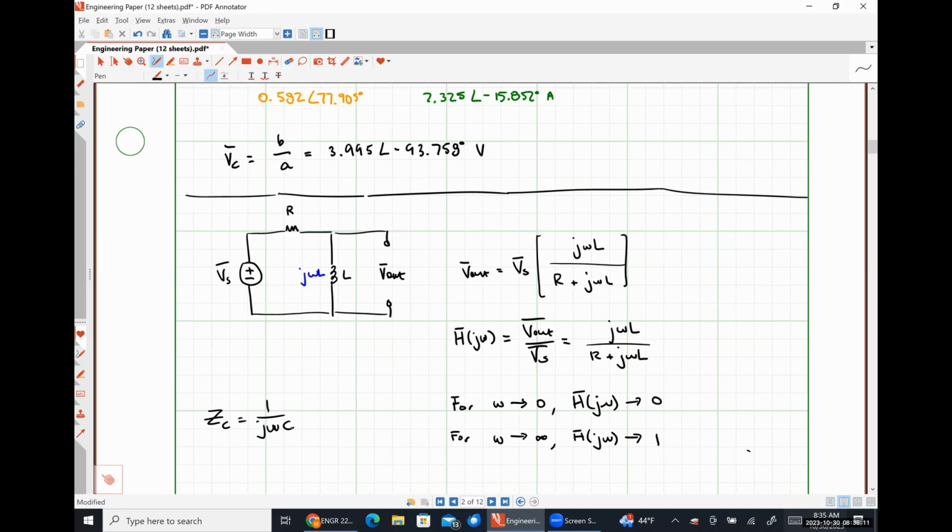So this concept of impedances might seem a little weird because we're treating capacitors and inductors like they're resistors, and they are, but they're frequency dependent resistance. And we can exploit that frequency dependency and do some really interesting things, like pass and attenuate signals and all that kind of stuff. If we have both inductors and capacitors, we can make neat things like band stop filters and band pass filters and all of that kind of good stuff.